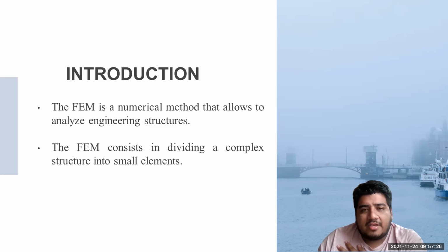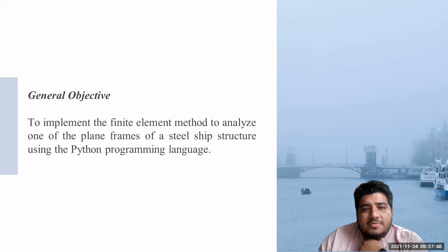The frame of the analyzed structure presents negligible deformations. They are less than 1 millimeter. The normal stress developed on the elements that compose the frames does not represent a risk. However, the elements that compose the deck develop stress close to the yield point of that steel. Next, the general objectives.